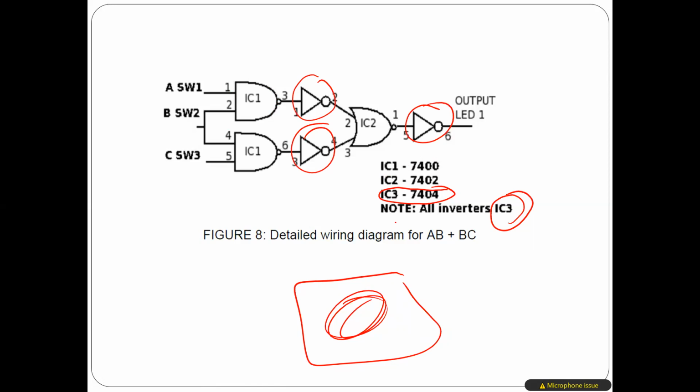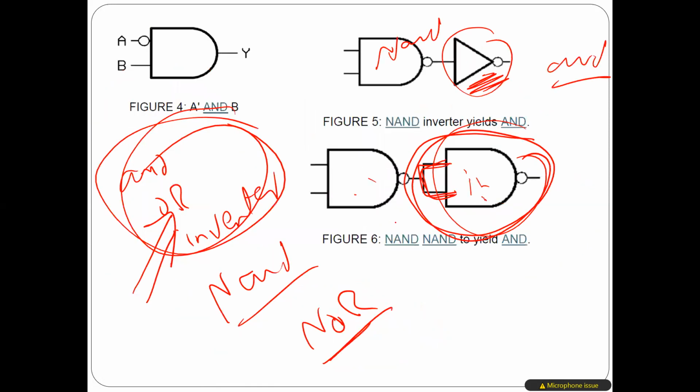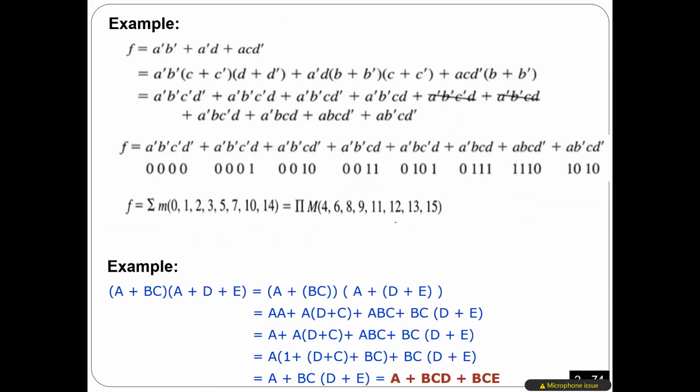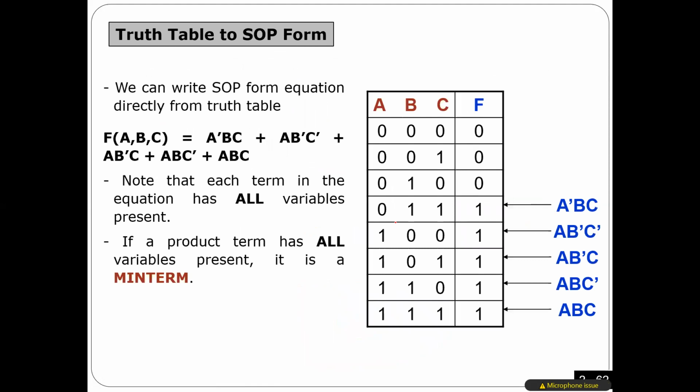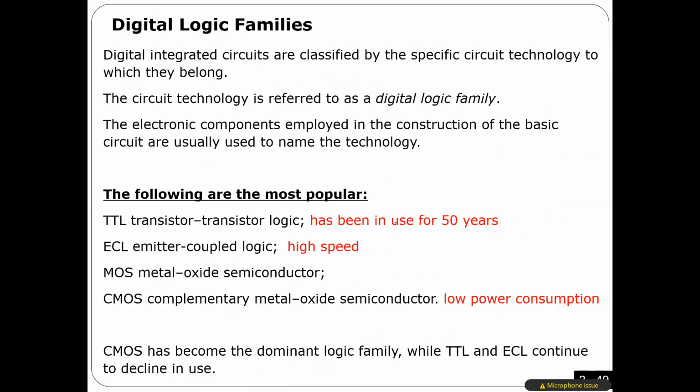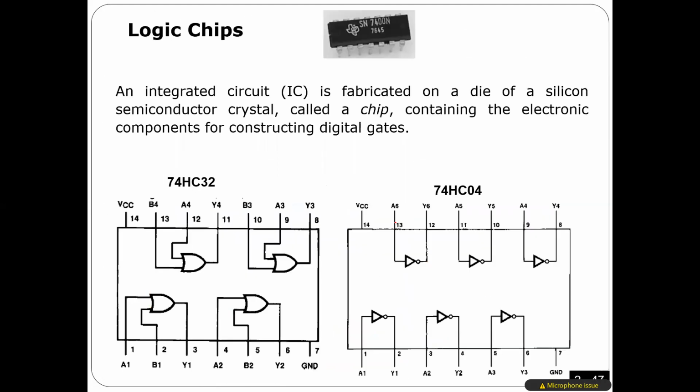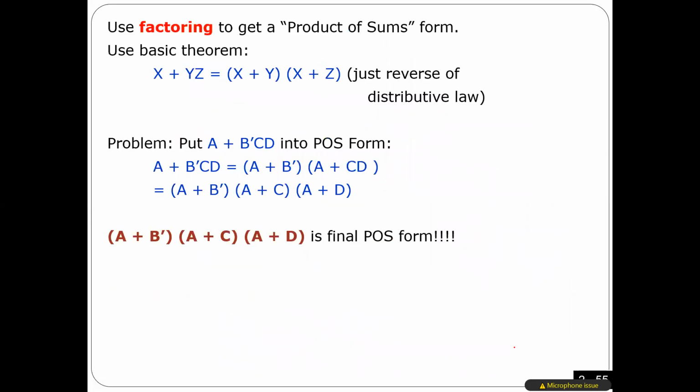Also the same thing. Let me look now. Actually, I think I put it before. Yeah, look here. Again, you have to connect this pin to 5 volt and this one to ground, and then you can use the gates. You have 1, 2, 3, 4, 5, 6, so 6 of them. I can use input, output, input, output, input, output, and so on.